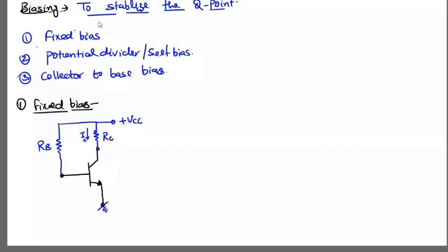We get another current called IB, the base current. Definitely, in the common emitter configuration, this voltage is plus minus VBE and this voltage is plus minus VCE. Am I correct? This is the simple common emitter. Yes, and I have applied only two resistances and one power supply, and this circuitry is known as fixed bias.